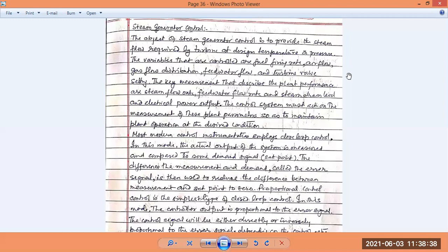This gas will carry the heat of the burning fuel or coal to your riser tubes, your air preheaters, reheaters, everywhere. This heat is being transferred by convection from the gas itself, not directly from the flame of the fuel.